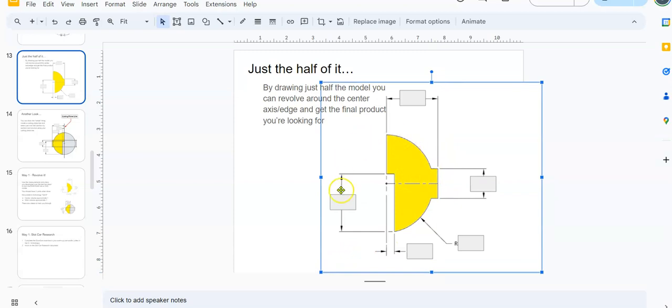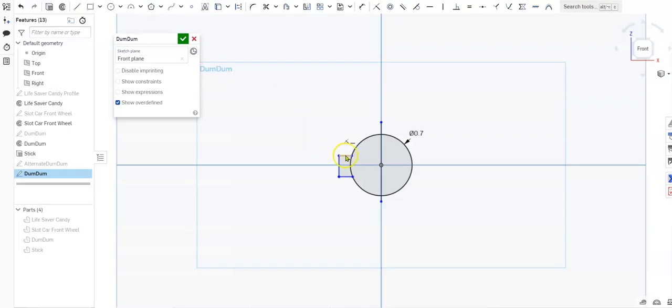So what we've drawn so far is the circle. And now I just added the 3 lines, this ring portion that's going to stick out. I want to make sure that that ring portion is symmetric top to bottom, so I'll use the symmetry tool. Shift Q on the keyboard is the symmetry. I click and release on the upper portion, click and release on the bottom portion, and then grab that horizontal axis. And you can see that's now symmetric.